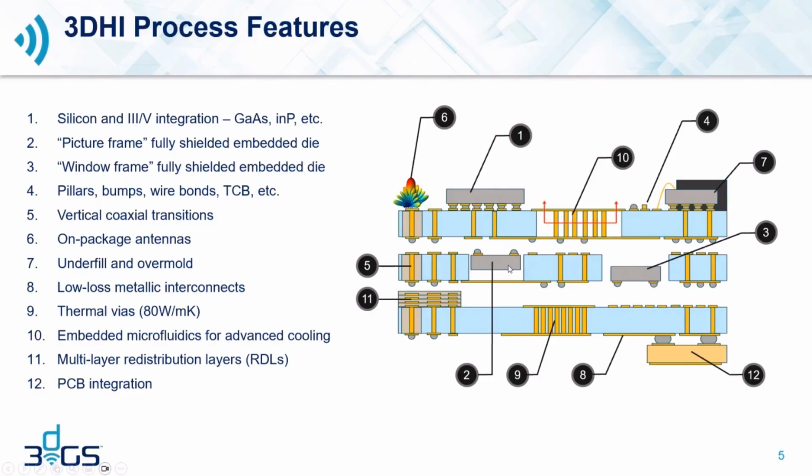And over here on the left, the picture frame, we still include the metallization layer on one side of the glass. Typically, we use this on the bottom or top layer of a module if we need a ground plane. So these are the two that we're going to be using today. Also for phased arrays, it's important in other designs where we want to include an integrated antenna in package. Again, not today, but other designs we have implemented successfully.